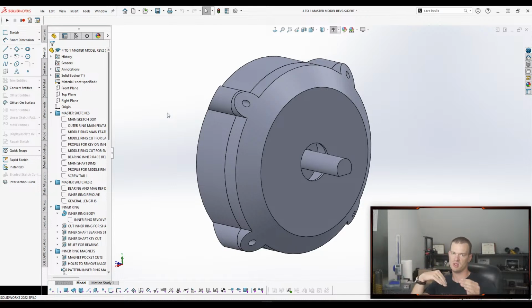it's a combination of the two, where you're creating a skeleton sketch part file that has your core sketch geometry in it, and then you're creating another part file that's going to be your master model, and that only has your organic stuff that's tricky to do curvature continuous without having the other surfaces there.